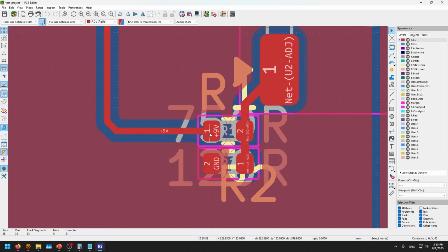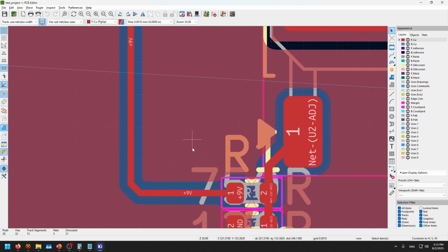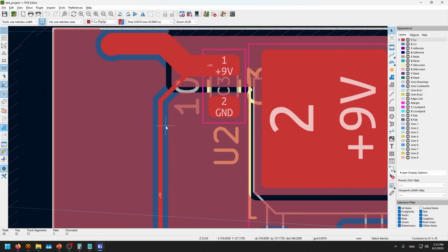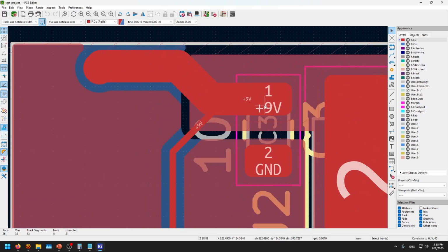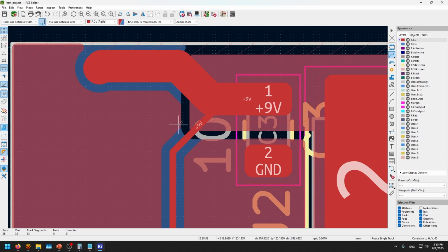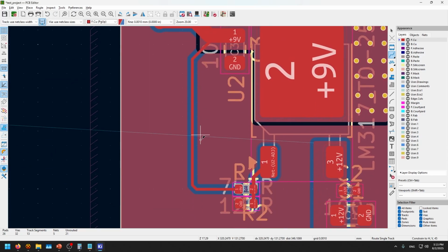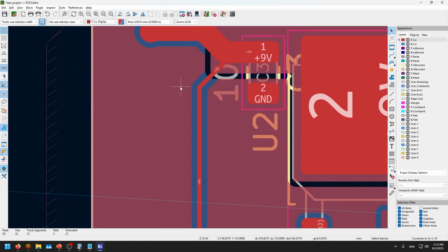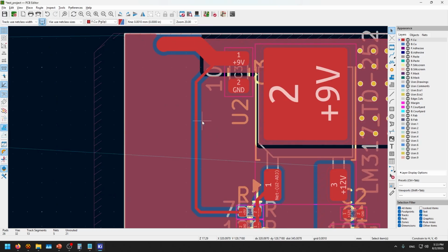And the feedback pin, look at this. The feedback trace is a thin trace coming from here, separate from the output, so that you do not take it directly from here, something like this. No, I take it from the polygon pour, a very small and tight layout. Now this feedback trace must be away from all noise generating devices, such as switching regulators and stuff like that. So that's a very nice tip.